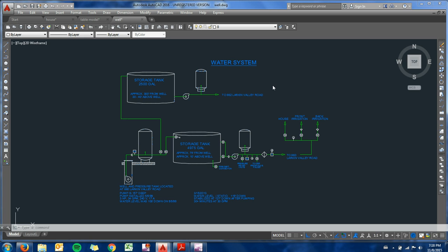However you're organizing your drawing, you're going to have things grouped together in what's called layers, which will have different colors and line types associated with them. They may or may not be set up to print, and depending on what color you select, they'll probably be printing in different thicknesses.